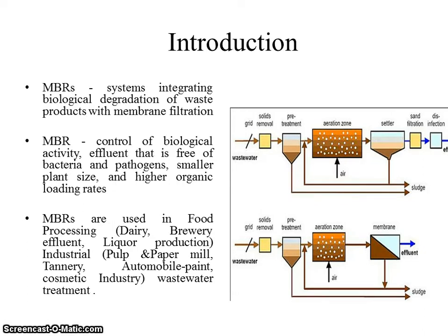To make you recall, in the last class we have already learnt about the stages in the treatment of wastewater. That is basically screening, grit removal, and PST, the primary settling tank, aeration, which will be a part of the ASP, and the secondary settling tank, followed by filtration.